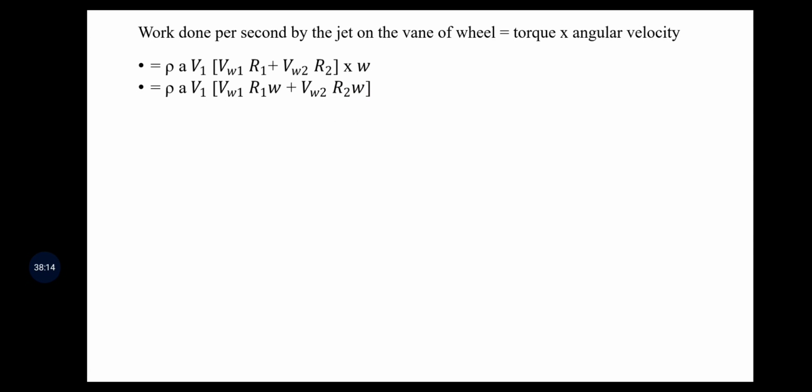We know that linear velocity is the product of radius and angular velocity, in general v equals R omega. Here, instead of v, the tangential velocity of the plate or the vane, or the wheel, is u. So u equals R omega, and as R1 omega is there, it means u1, and R2 omega means u2. This is applicable only when beta is an acute angle.